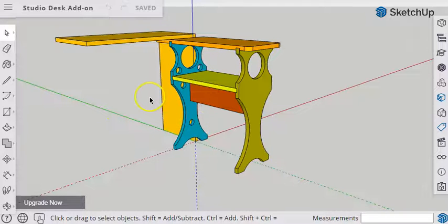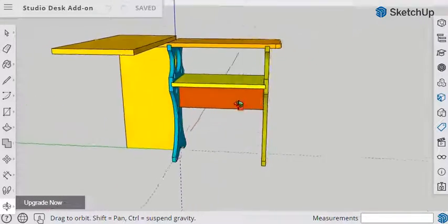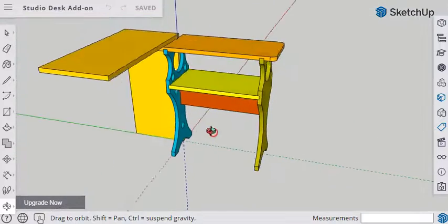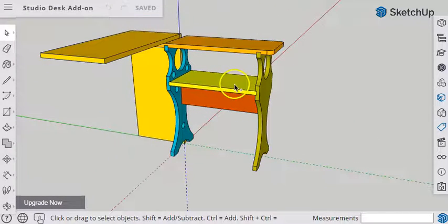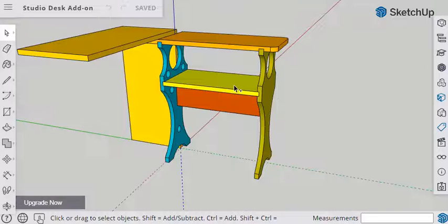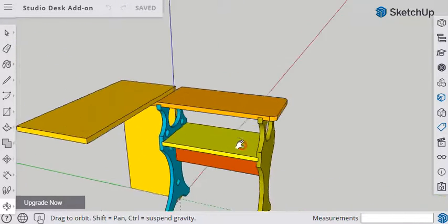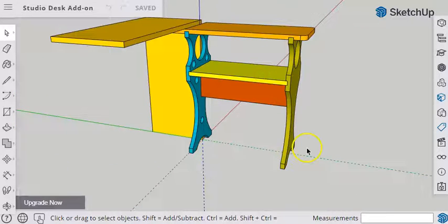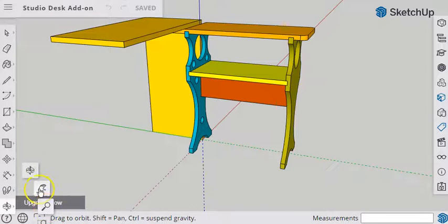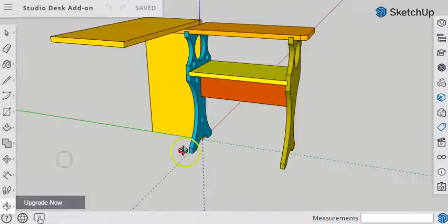So I'm going to hold down the wheel on my mouse, and that turns it into a camera rotate, so I can move around. I let go. I can hold down Control and wheel in, and that zooms in. I can hold the Shift and hold down the wheel, and I can slide up, down, all around, that sort of stuff. So that's the kind of navigation I'll be using. You'll get used to using the Control, the Shift, and the wheel button to do a lot of stuff.